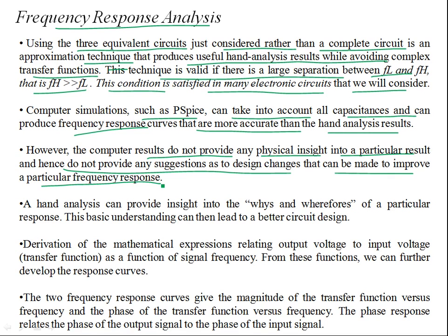So if you are going to, for example, simulate your circuit, you're going to do the transient analysis or the linear circuit analysis with all these capacitances. The computer is going to give you the frequency response, but to gain insight into why and where you have to change your circuit to meet the design requirements, there's no insight in these results. So to have a better insight, you must be able to do the hand analysis.